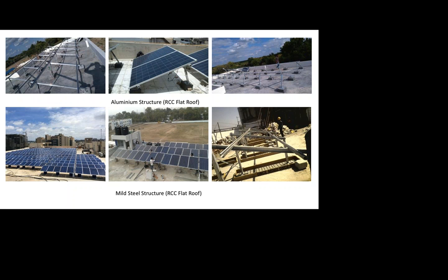Hilti comprises of two things. One is the bolt, second is the chemical. The bolt, as I told you, is based on the uplift which is coming on the structure, what is the force, and based on that we get the bolt design. Secondly, the chemical is basically how much sealing you require to integrate that bolt with the roof. Now, this chemical is non-porous.